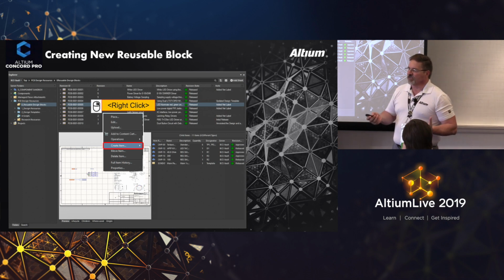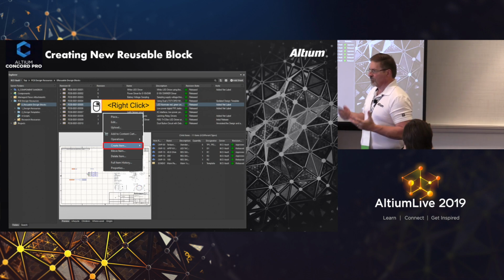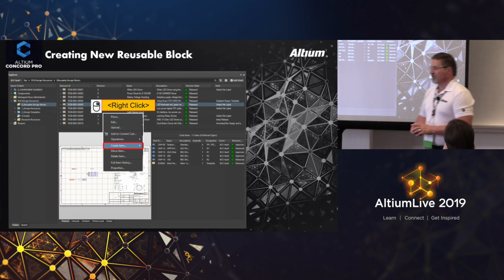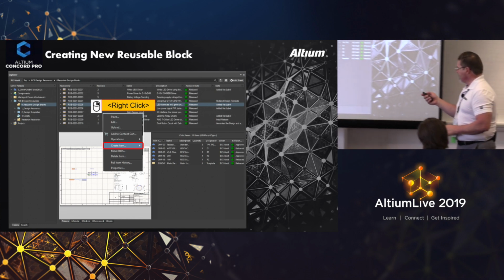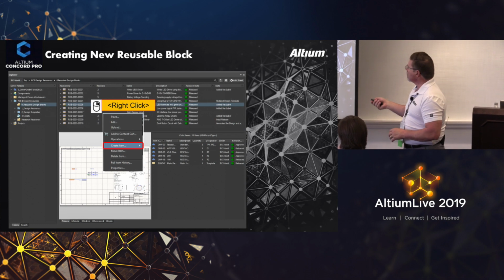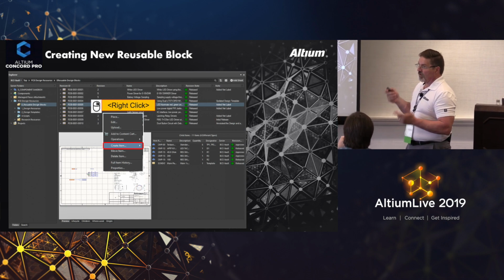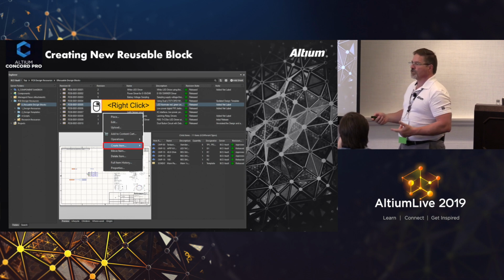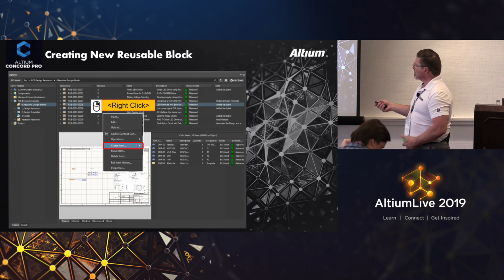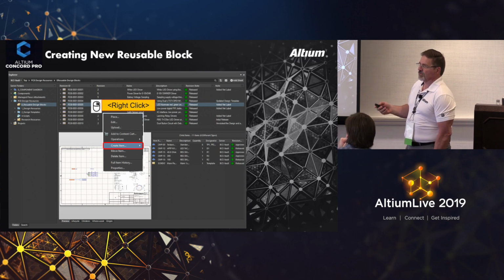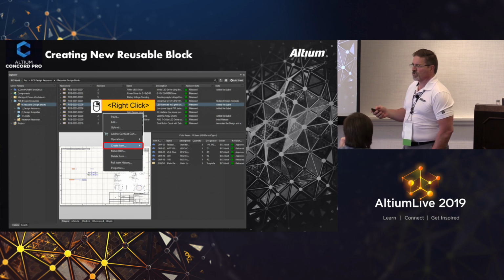There's no management of your component information, of availability especially, okay? So keep in mind that this sourcing right here, when you use your components from your library, also manages your availability, whether that's a good choice or not. So these components will come in labeled as, okay, this may not be your best choice here.